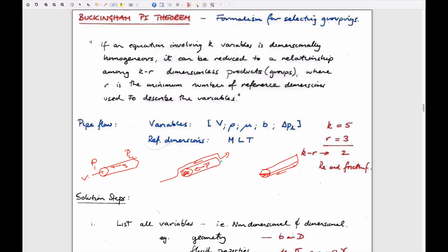So we introduced pipe flow using dimensional analysis. We know that for dimensional analysis we have to do a couple of different things. We can figure out how many dimensionless groups are made up by looking at how many variables describe our problem. Flow velocity in the pipe, the density of the fluid, viscosity of the fluid, a diameter of the pipe if you like, and the pressure gradient, dP/dL in this particular case, I think it was. So these could be combinations of variables.